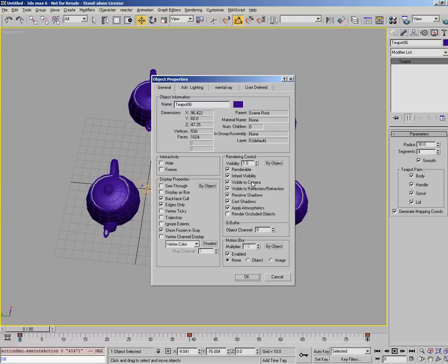So as an example, something that you could do with a vampire, if you're doing a scene which uses ray tracing, is you could turn on visible to camera, i.e. you can see the vampire, but you would turn off visible to reflection and refraction, which would mean that the vampire would not reflect in any ray trace surfaces. Vampires don't appear in mirrors. Well, you can do the same thing in 3D. You can actually get objects to appear exactly where you want them to in a scene.